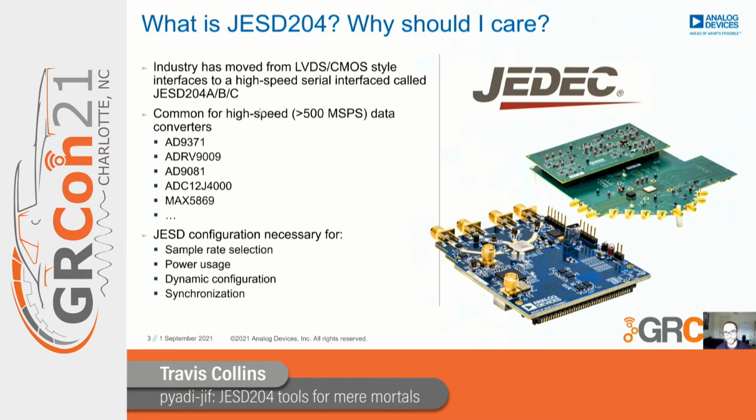Now, why should you really care about this, or why would you want to know about JESD at all? If you're changing the sample rate, if you need to reduce the power of your current device, if you're using a high-speed converter or transceiver, or if you want to move between FPGAs, say from a Xilinx kit to an Intel, or to a different grade of FPGA, you really need to understand how JESD works and the different elements that are involved when manipulating the clocks in JESD-based devices.